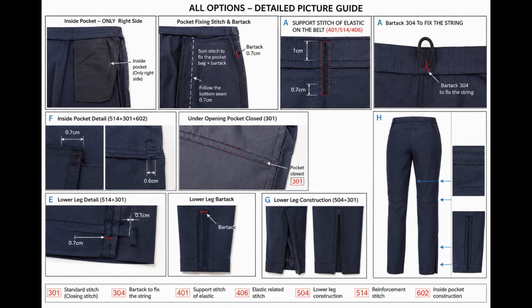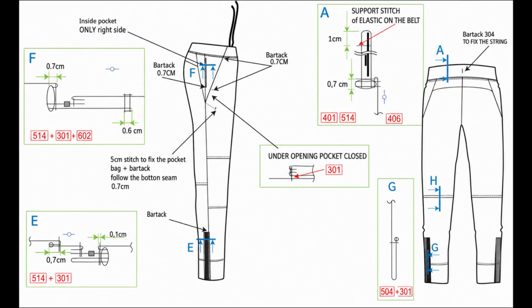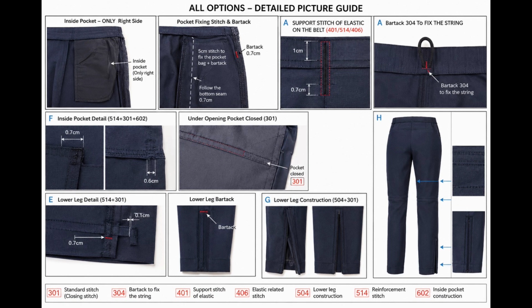5. Bar tack 304. Fix the fish string. At the back waistband area, the drawing indicates bar tack 304 to fix the fish string. Operation bar tack 304. Purpose to secure fix the fish string attachment. The bar tack must be positioned at the indicated point on the waistband. The bar tack must firmly hold the string so that it cannot pull out during use. The waistband stitching should remain clean and straight around this area.